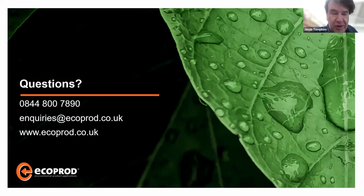And if you're worried about Legionella because of spray taps and things like this, well, hang on a minute, you should be worried about Legionella within the whole system, because it's not the spray tap that's doing it, it's the temperatures within the system. So you need to be looking at purging and flushing, all of those things. So in my view, having a water management strategy that looks at water efficiency is also majorly beneficial for hygiene. The two things, in my view, are complementary.